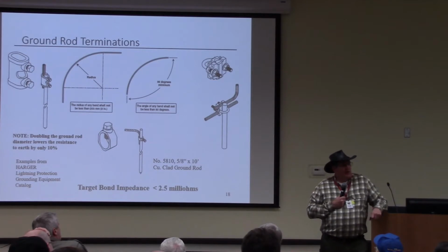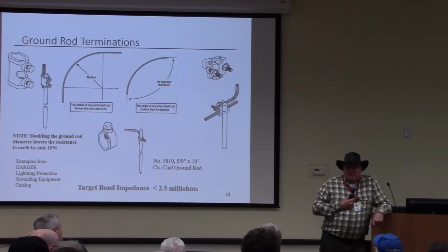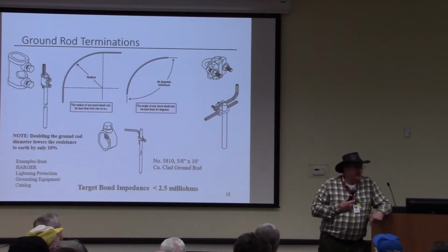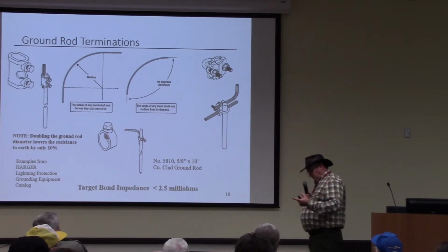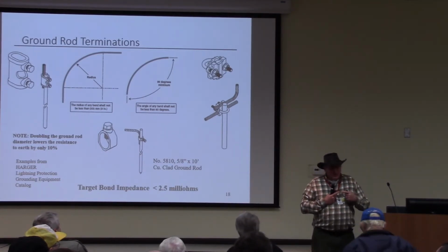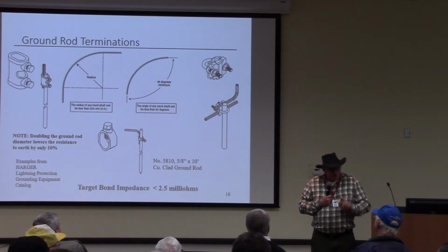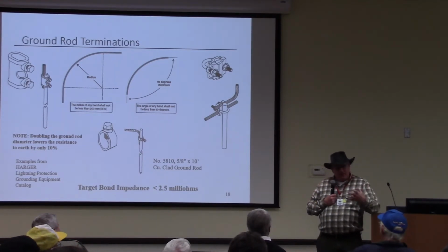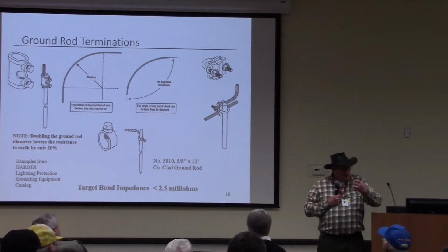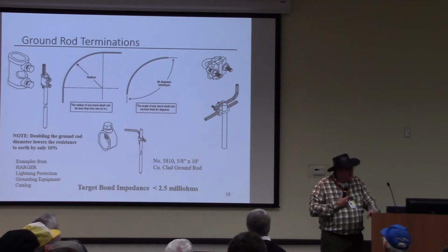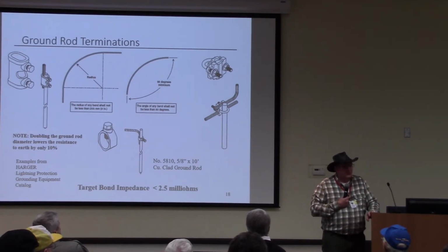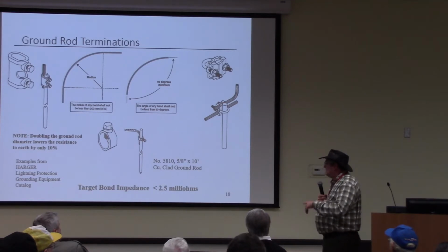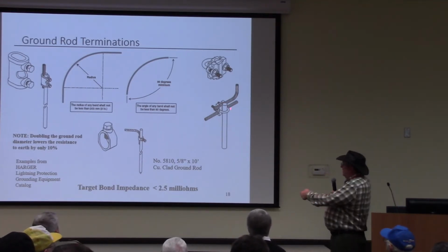The weave is such that they try to weave it to minimize the amount of inductance, but it also increases the surface area, because if you've got 24 strands of 18 gauge wire, or 24 strands of 20 gauge wire that's woven, it's got some airspace in there, so you're going to have more surface area. And when the lightning strike's occurring, the lightning channel and the arcing inside that cable would make a plasma type situation where it can carry more current without damage, and it'd be a higher surface area. It'd also be less inductance, so you'd have less of a voltage drop potential between 2 points.